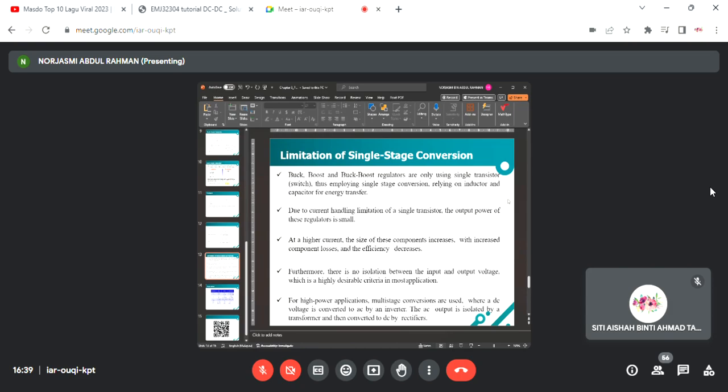When you have fewer components, then you have less parasitic and fewer losses. For the converter, mostly the losses are associated with the switch. At the switch there are two types of losses. We call them the conduction losses and the switching losses.